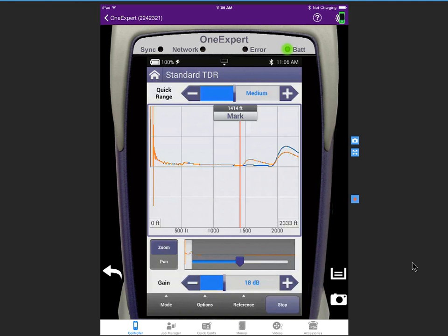over and over again. The reason for this is it's unbelievably easier for your eye to catch a difference in a line if it's being written over atop itself, as opposed to a new or fresh line given each and every time. This is clearly depicted on the screen with the blue portion of the trace being what we were looking at before applying the stress signal, and the orange, what we're looking at now live after the stress signal of 120 volts has been applied. Clearly the jolt of voltage has introduced a high resistance open.